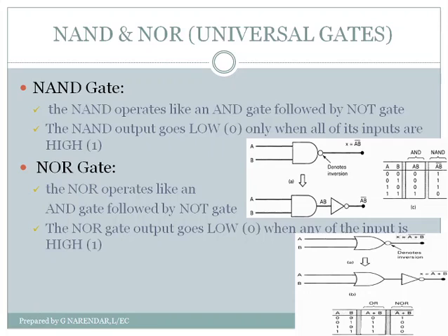And 1.0 is 0 and 0 bar is 1. So in this case also the output of NAND gate becomes 1. But see the last combination, when A equal to 1 and B equal to 1, so X equal to 1.1 bar. 1.1 is 1 and 1 bar is 0. So the output of NAND gate, when both the inputs are equal to 1, the output becomes 0.